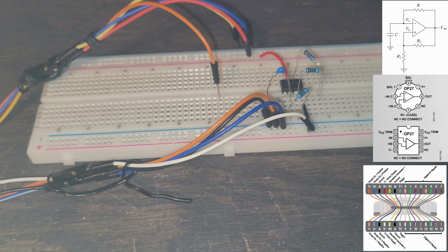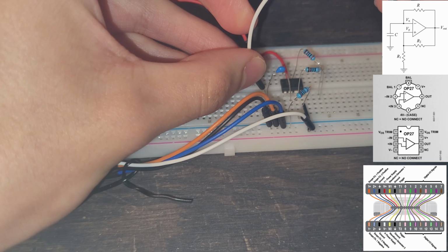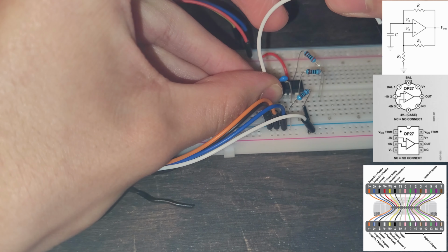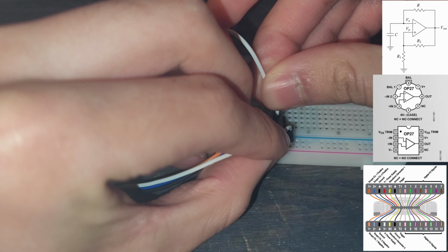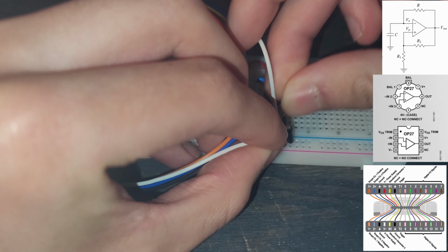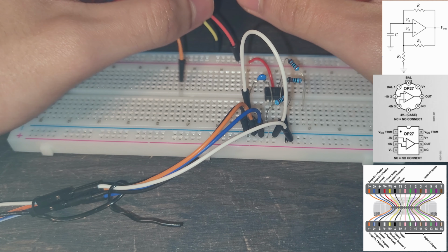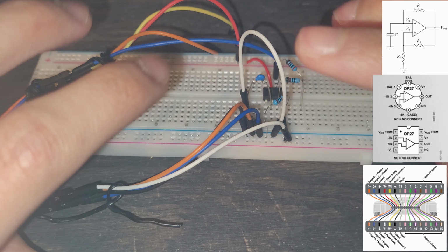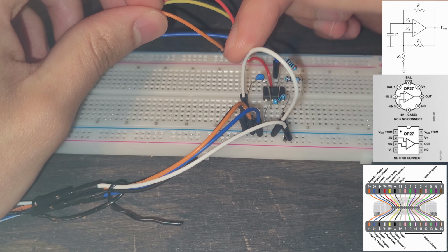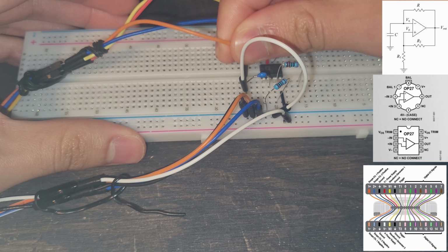And so what I'm going to do is actually grab a jumper wire, and I'll just grab a white one, and I'm going to go from here into our ground. That way we are going to ground out this capacitor, and so that is going to be our values. Now we want to measure our voltage output, so this is going to go here. Our voltage input in this case is going to be the capacitor part, so we're going to take this wire and we're going to put it in the same column as our capacitor.